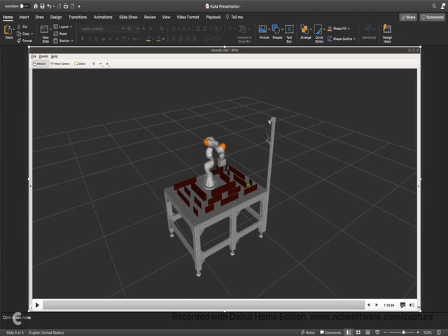To conclude, in this project, I demonstrated a solution for obstacle-free motion control in a 3D environment for a KUKA robotic arm. RRT star was used to determine the shortest obstacle-free trajectory from the starting point to the destination.